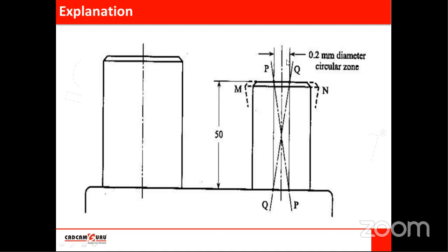So this is the ideal position. If you see this component from the top view, you will see only a point if this axis is ideal. But again, we know nothing is ideal. So this cylindrical feature may have change in orientation or deviation in any direction around this axis. From the top view, we may see a small circle.